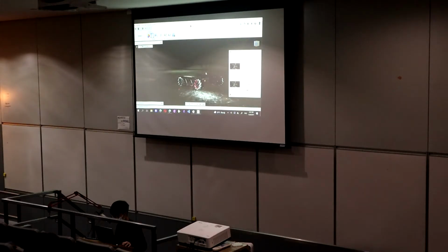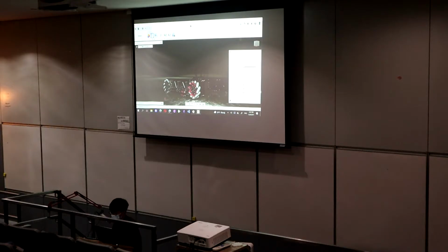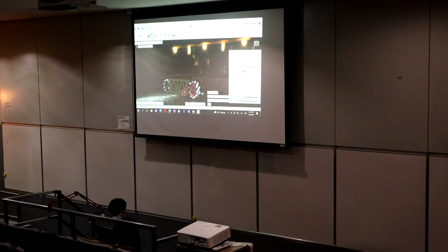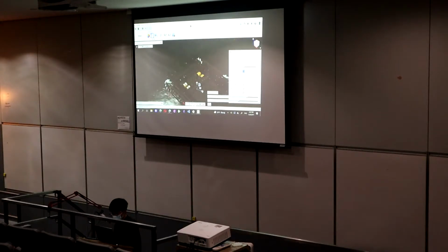And the cool thing is that when I apply appearance to one, all of them change together, which is pretty cool. It's also super useful, and it highlights the importance of being consistent when you model in CAD. If you're using random parts that aren't from the same file, you wouldn't be able to have this feature.